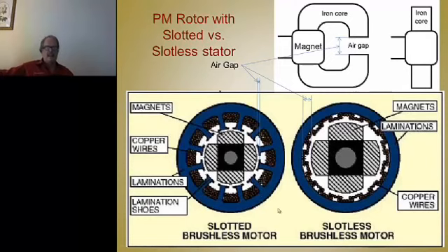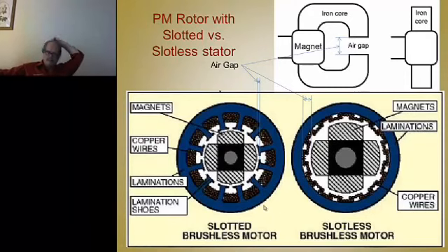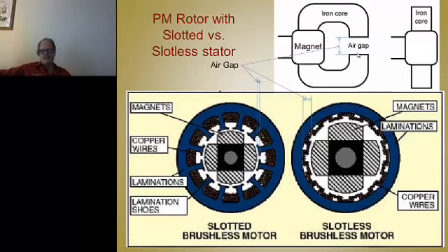But to be fair, I want to make sure that I'm not trying to disprove Faraday's law there, or any of the other laws. I want to show the same motor with the same rotor, by the way. Maybe the pole's a little thicker, but similar cross section, except I've cut the teeth out. There's no teeth in between here. So the coils are kind of spread out uniformly. They're laid around here. So now here's the air gap in this concept from the previous lecture. Here's the air gap in this one.